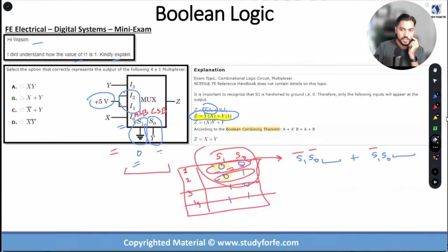Okay. All right. So we are here. Now, what's the next step? How do we fill in these blanks? This is a multiplexer, correct? So when my switch entries are input 0, 0, low, the first scenario, which of these inputs are going to show up on the output? So 0, 0 is going to select what? I0, I1, I2, or I3?